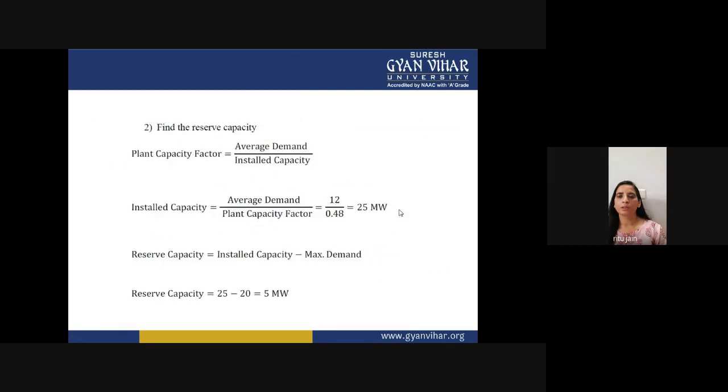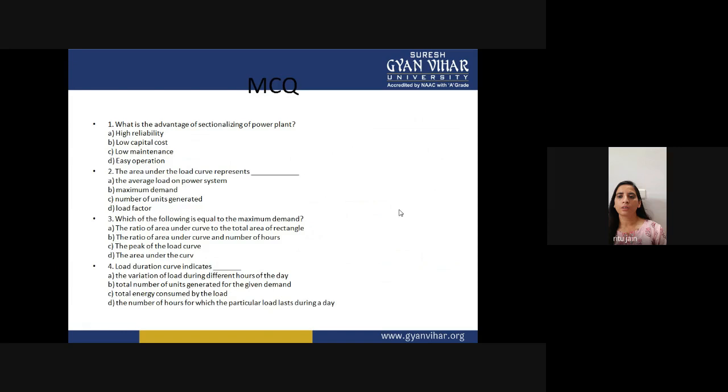So this is all about this lecture, and I think you are able to calculate your load factor, your diversity factor, and your maximum demand and average load, plant capacity factor. Now these are some questions which are based on your previous and this lecture.